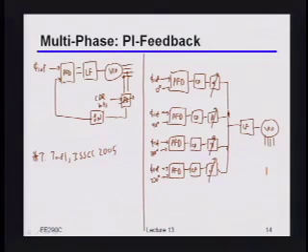And remember, most of the time your phase errors are not going to be larger than a clock cycle. In fact, they're probably going to be smaller than 90 degrees, and hopefully much smaller, because if they're bigger than that, you're probably making errors. So what's nice about this is that this node right here is low bandwidth. All of the weird transient junk and errors that I might be picking up here gets smoothed out by working on that low bandwidth node.